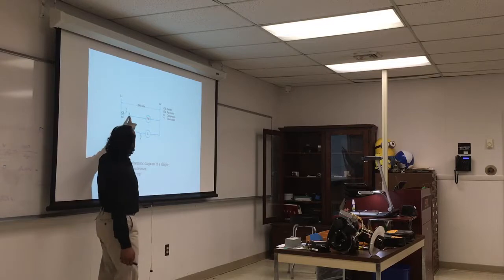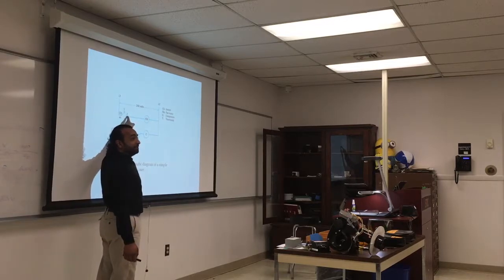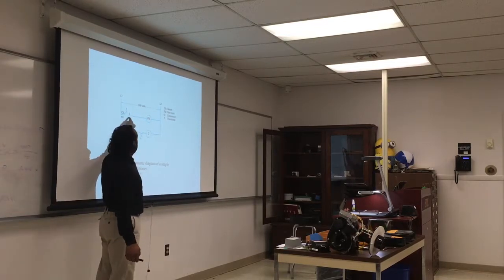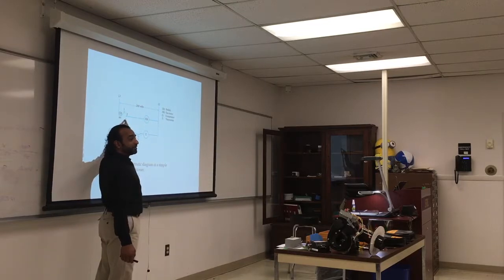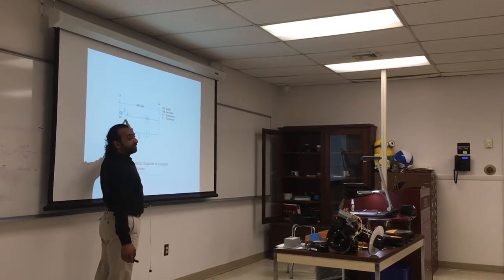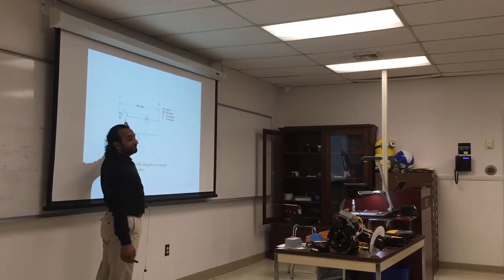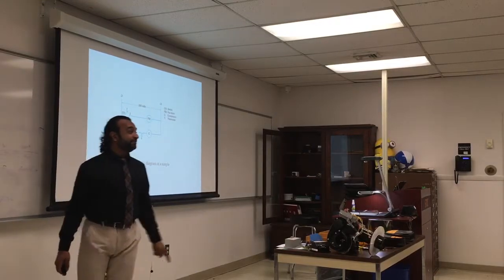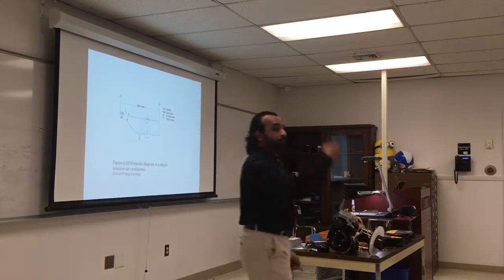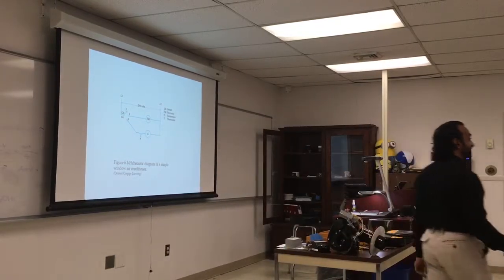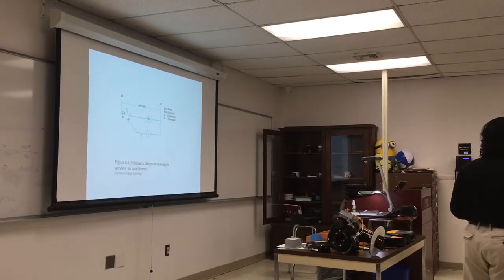And these are the switches. If you connect one of them, you only have fan only. If you connect 2 of them, it will be fan and compressor. And you cannot connect the compressor by itself. What would happen? No, it will turn on by itself, but there is no air circulating and it's going to accumulate frost, because the air is not moving.